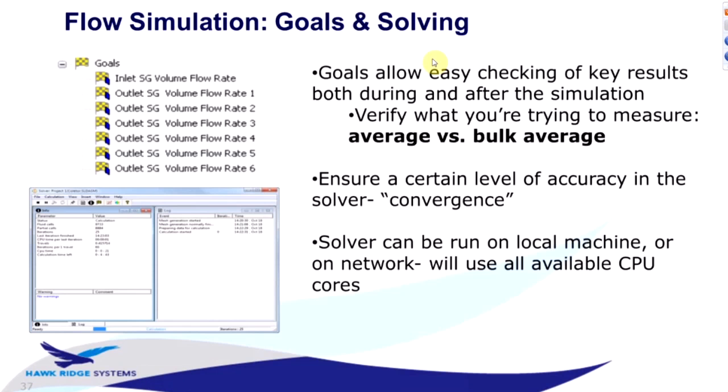So what are the goals? Well, the goals are basically the key parameters that you're most concerned about in your simulation. What are the key results you want to know? If you were running a stress analysis or some other kind of simulation, they're typically called sensors. So slightly different name, slightly different purpose. In addition to making it easy to check the key values from your simulation, they also ensure a certain level of accuracy in the solver for flow simulation.